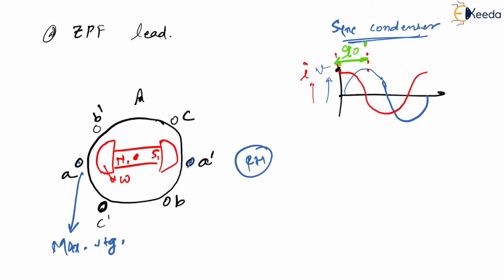Now, what is happening? If you see, if you stand here at voltage maximum, you understand that current maximum has been already gone. Current maximum has been already gone 90 degrees before, which means definitely current maximum is going to be here. Now we want it in opposite direction, so if this is dot, then definitely this has to be cross and this has to be dot. Correct? Now if you think of the MMF because of this armature, by using the same right hand thumb rule, you get that this is going to be this way, which is going to be FAR.